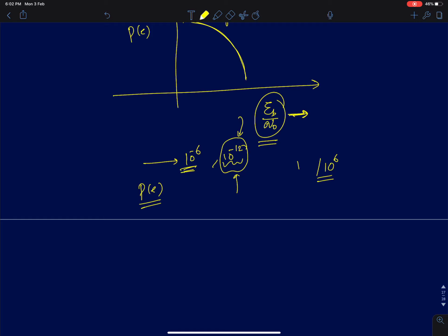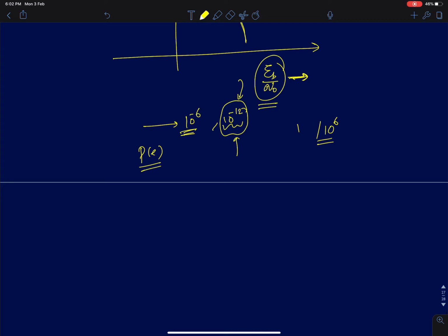If you recall from your previous lecture, if you want to increase your Shannon capacity, which is your bits per second, power was not really helpful, because even if you increased your power exponentially, there was only a marginal return. There was the law of diminishing marginal returns, if you recall. But if you increase your SNR, on the other hand, the bit error rate will go down exponentially. That's the main difference. You may not gain in terms of speed, but you will gain in terms of reduction in probability of error. So these are the points to keep in mind.